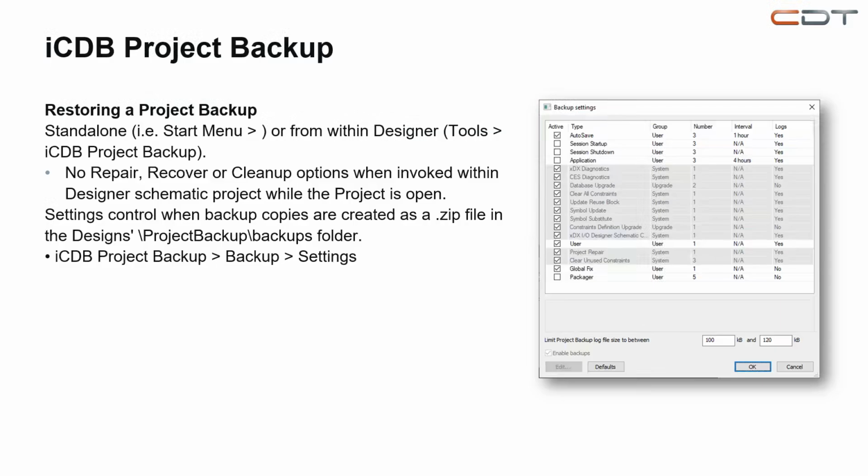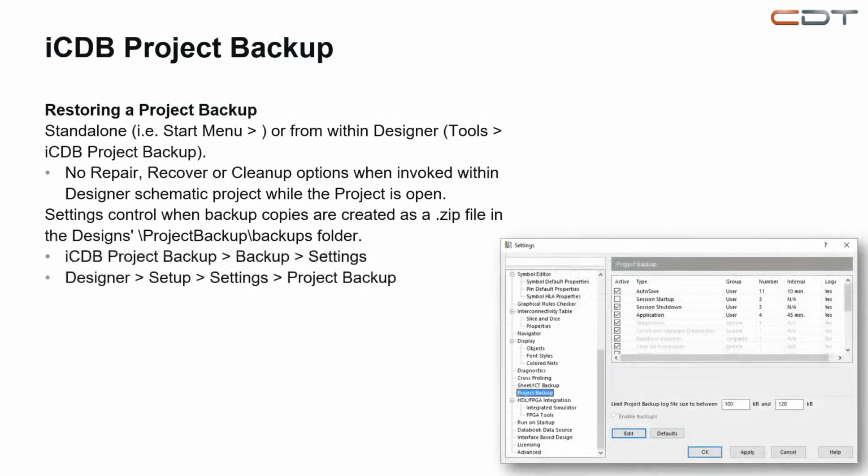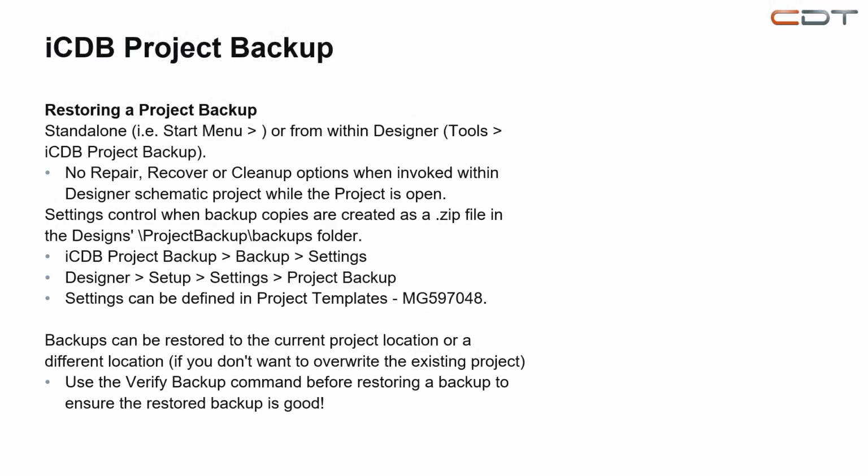You can, as I said, run iCDB project backup either from the start menu or within Designer. Until the project is closed, you will not be able to repair, recover, or clean up, because you need to close it. In Designer, you can go to Setup, Settings, and in Project Backup you can also adjust this setting for your own good. Backups can be stored in the current project location or a different location if you do not want to overwrite the existing project. And once you restored a backup, use the verify backup command to be sure that everything is okay.